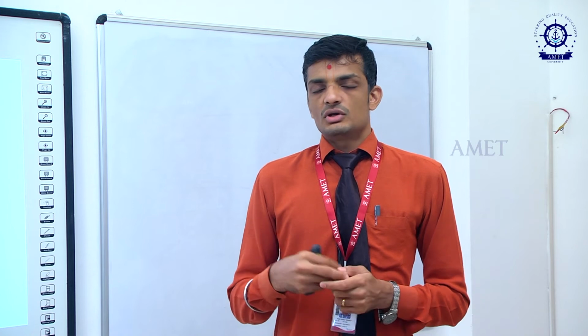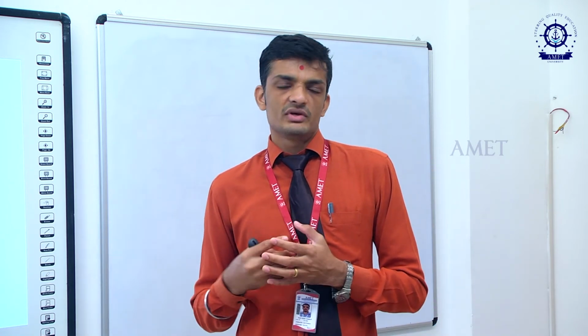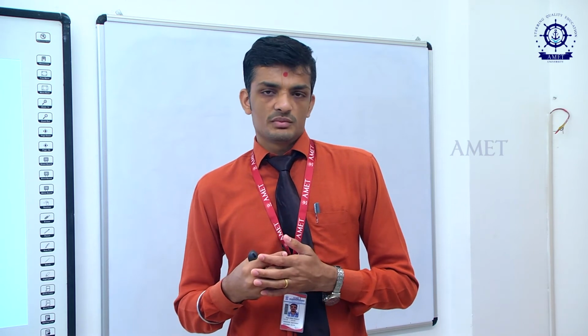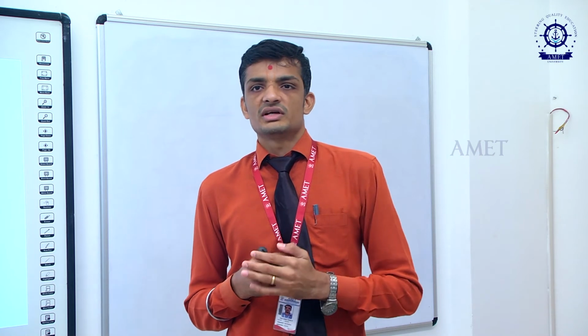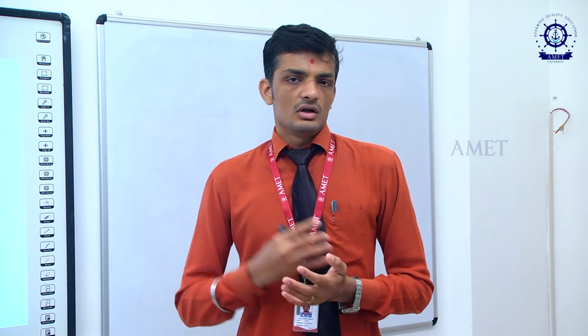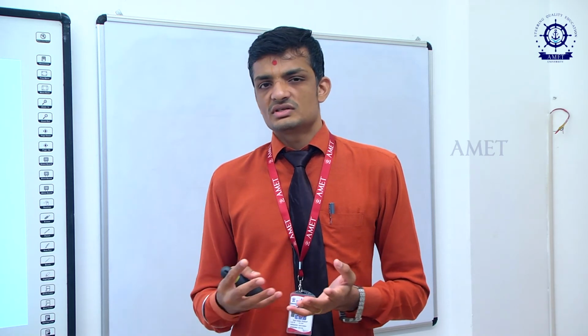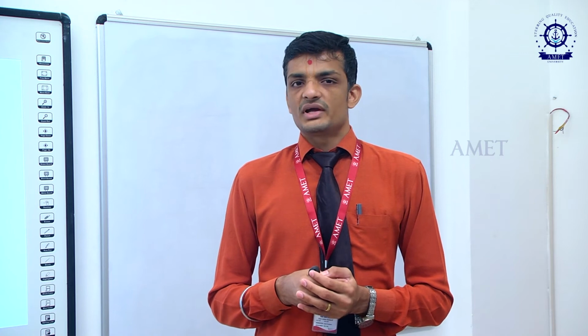The other part is called line load. So the best example of the line load would be if you keep something heavy which doesn't occupy much breadth, but it occupies the length, correct? So the load acts along the length, and normally what we do is if it is uniformly distributed along the length, that particular load is considered as a UDL acting at the particular location. So that is my line load.